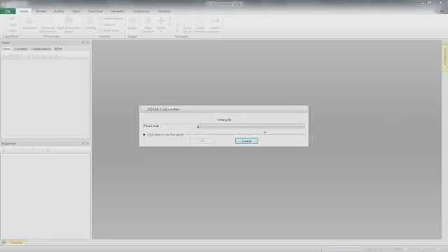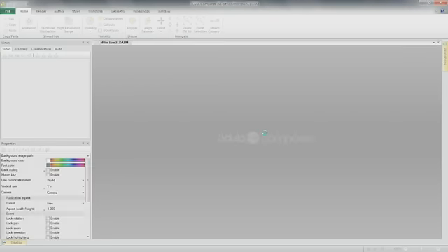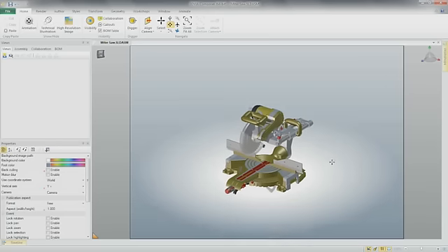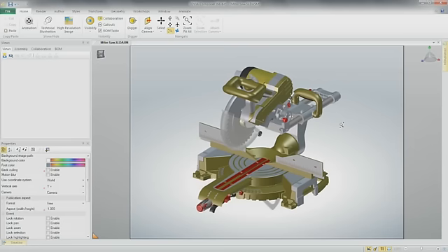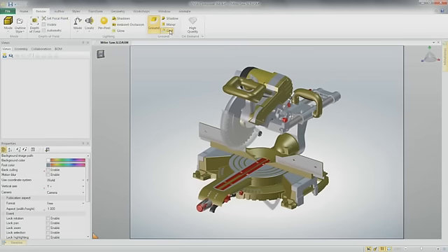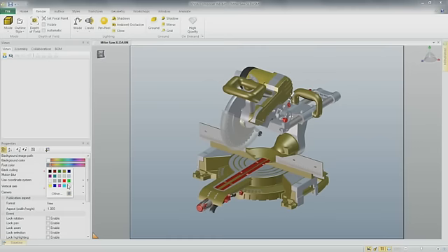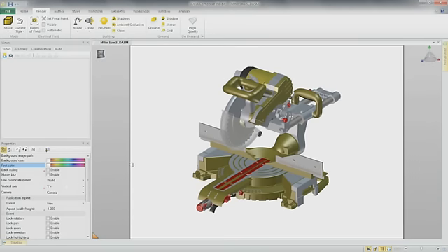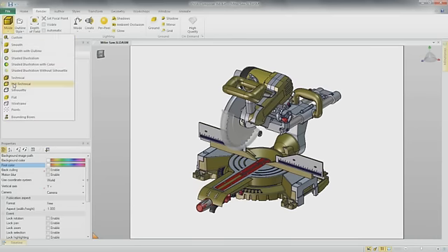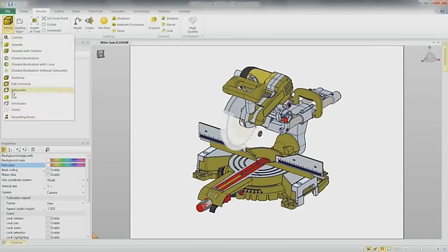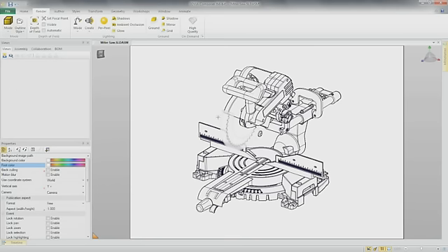Once the 3D data has been opened inside of Solidworks Composer, we can get to work creating the different views for our product manuals. We can change a wide variety of graphic settings, from the grid on the floor to a mirrored surface and shadows. In our case, we'll use a simple white background, as we're going to be creating a more traditional image style. We can also change the graphic style of the 3D model itself. For example, a flat technical style or a more traditional silhouette style.